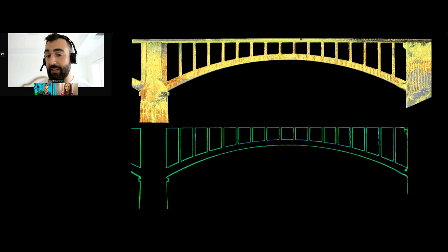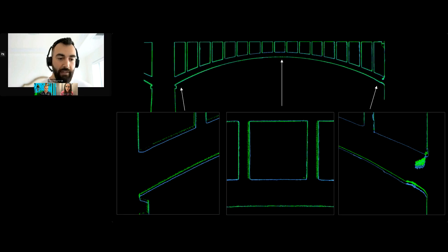And then taking a look at a section as well, the whole profile of the elevation, we'll see here that it becomes fairly obvious that the photogrammetry point cloud is stretched vertically, right? That is not uncommon to see. The z-axis is always more difficult to get right. In the center of the bridge, you can see that the 2 point clouds are well aligned, but on the sides, the photogrammetry point cloud has less alignment, and specifically less alignment in the vertical.